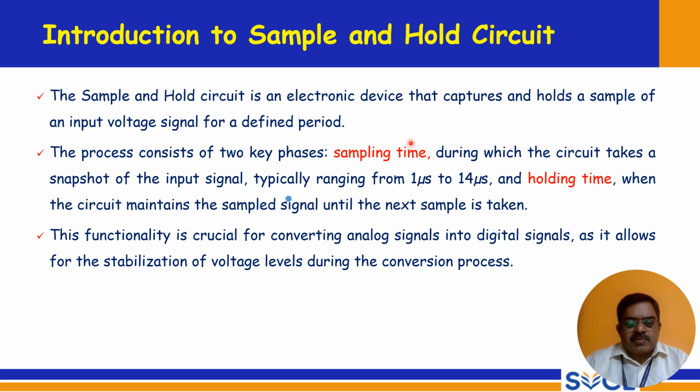One is sampling time, during which the circuit takes a snapshot of the input signal, typically ranging from 1 microsecond to 14 microseconds. And holding time, when this circuit maintains the sampled signal until the next sample is taken. So until the next sample is taken by the circuit, it holds the initially taken sample.